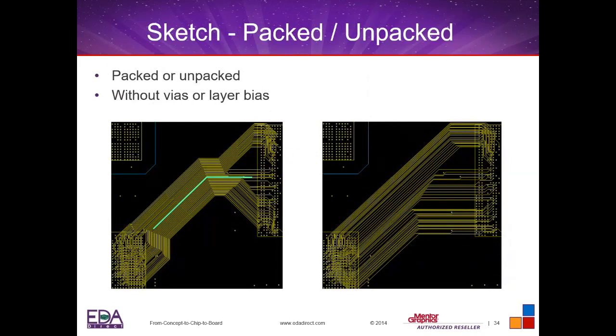Now there's two kinds of levels of sketch routing. We've got packed and we've got unpacked. Packed works really nicely when you want to pull all those lines together, as you can see here on the left-hand side. Very nice, tightly integrated.